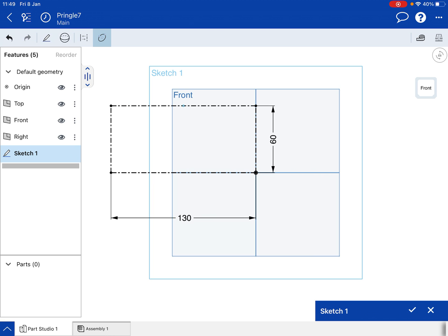Okay, let go there, drag out my ellipse, take it to the edge of the shape there. You can see it locks onto the edge there. So it is now 130 millimeters wide because the construction line is there. And then I can drag it down till I get it to about that edge of the line there. Cool, okay.